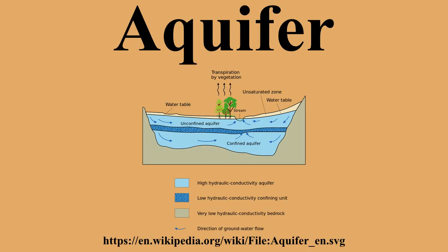Salination. Aquifers in surface-irrigated areas in semi-arid zones, with reuse of the unavoidable irrigation water losses percolating down into the underground by supplemental irrigation from wells, run the risk of salination. Surface irrigation water normally contains salts in the order of 0.5 grams per m³, and the annual irrigation requirement is in the order of 10,000 m³ per hectare, so the annual import of salt is in the order of 5,000 kilograms per hectare. Under the influence of continuous evaporation, the salt concentration of the aquifer water may increase continually and eventually cause an environmental problem.